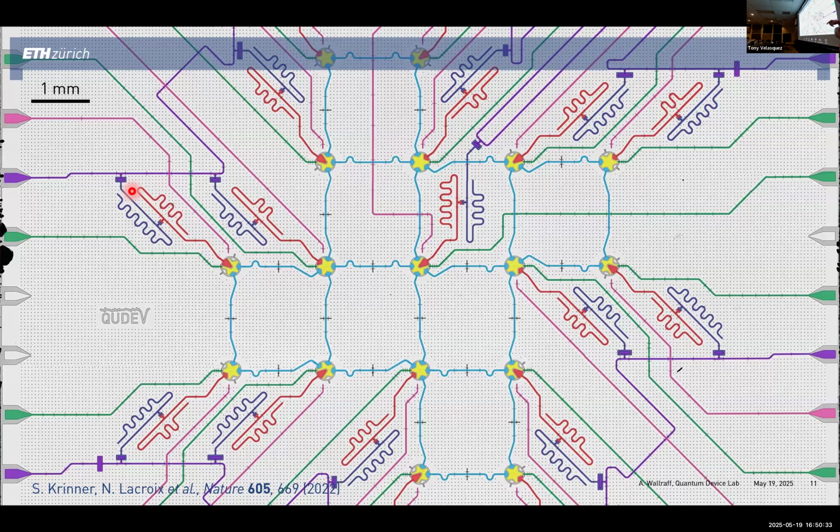And then the other question was about what property allows frequency multiplexing. You essentially frequency division multiplex. The readout resonators that you pick up here are designed to be at different frequencies, and that's the typical thing that we would do.